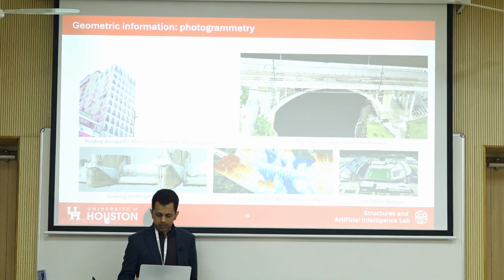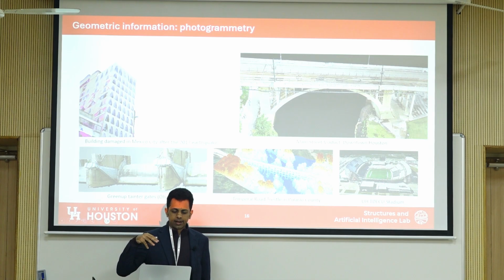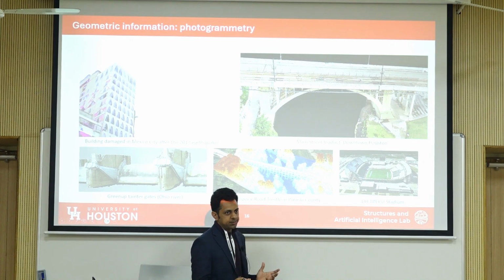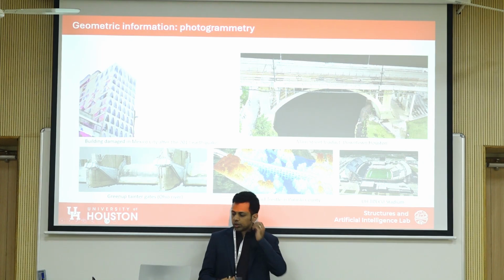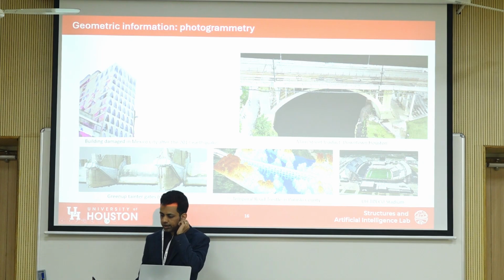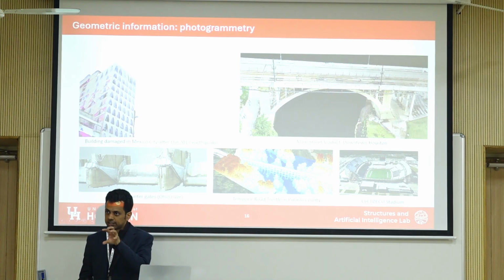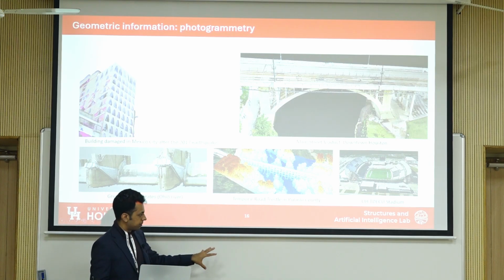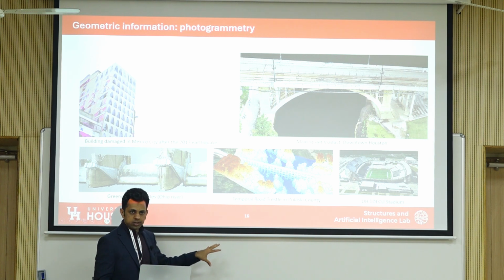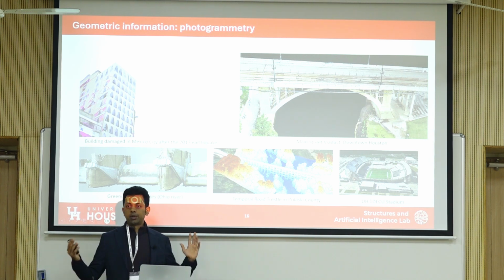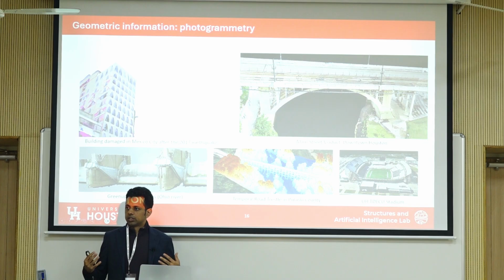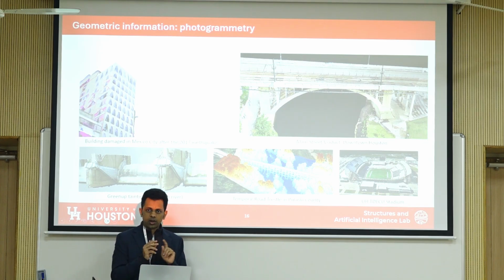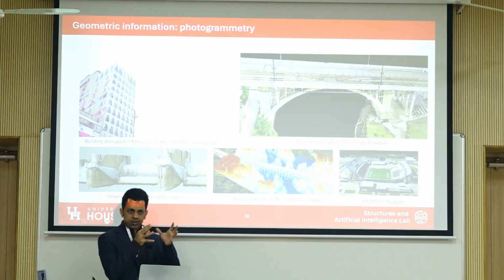So I'll talk about how to set up your data collection strategy, because there are many things that you need to account for. If you're looking for defects, then you need resolution very close to the structure. But also, if you're looking for geometry, then you need to be far enough so that you can identify parts of the structure that are the same.